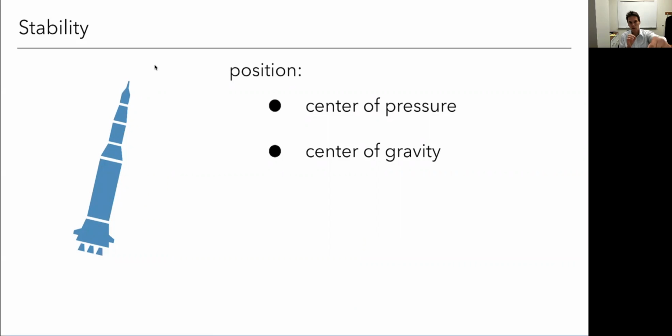Okay, so it's in front of, for a rocket, because we're going vertical, same thing, but we say the center of gravity needs to be above the aerodynamic center. That's the same idea here, right? So let's say here's my rocket, and I've kind of exaggerated it. Say this was my free stream velocity, so this would be the angle of attack. That's going to be undesirable. I want my rocket to be essentially at 0 degrees angle of attack the whole time.